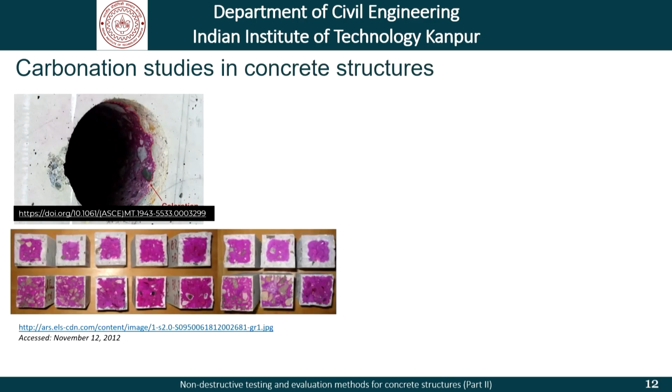Now, we've often talked about carbonation studies in concrete. Here is an example where a core was extracted from the wall here, and immediately phenolphthalein solution was sprayed. So we can see that this depth here is the depth of carbonation that can be observed. A similar thing under laboratory conditions is shown here.